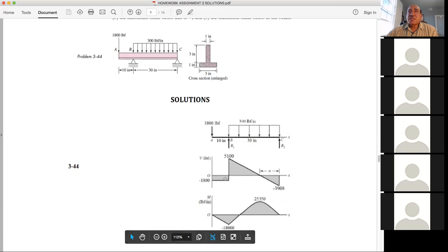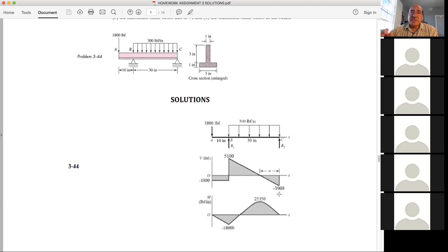So you have a shear stress at this point, which is pretty bad, and you have an axial stress at this point, which is also bad. So the idea here is to find the shear stress, which is VQ over IB that we have in the lectures, and that will be the worst point. And the maximum moment here, M times C over I. And then we can also, if we have shear force giving us VQ over IB here is a transverse shear, and we have a moment minus 18,000 here.